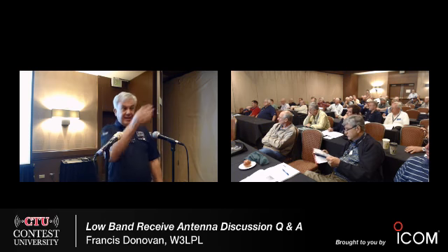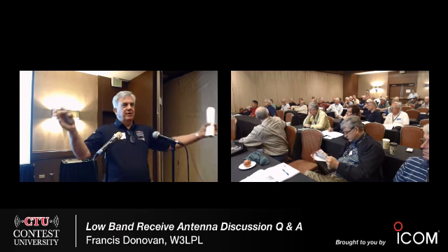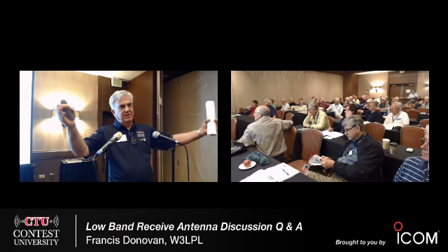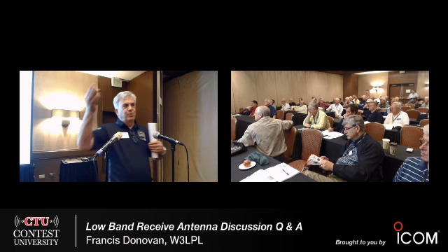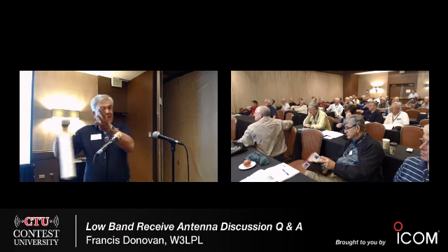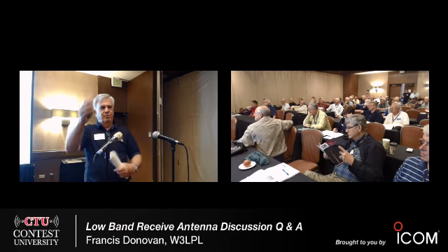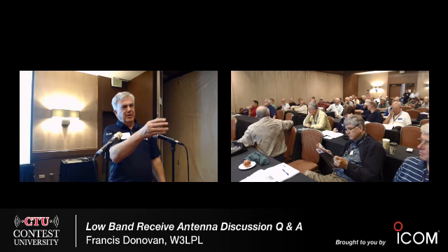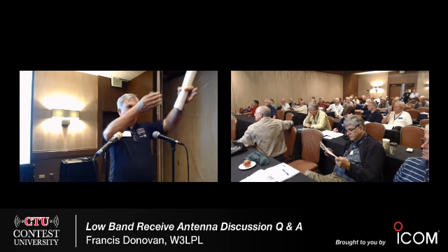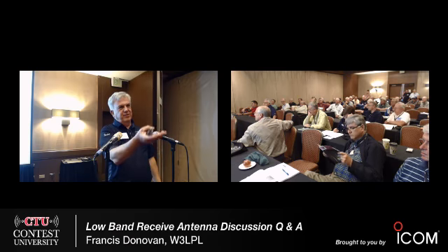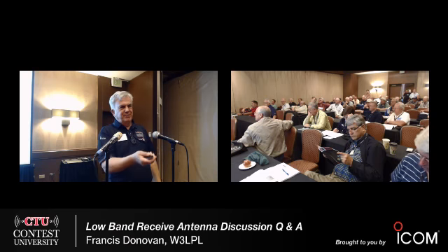Fabulous antenna. But you're pointed right at a power line, and it has a vertical wire running down. So it's got all the really bad characteristics. The beam width of a 540-foot Beverage is roughly 60 degrees. So you have to move the antenna, just as if you had a Yagi, far enough so you're down on the side lobe of the Beverage rather than boresighted right at it. And keeping in mind that a Beverage has a 60-degree beam width, maybe you could also change it so it's pointing further to the side. So you have to take advantage of the side lobe. Details are up to you.